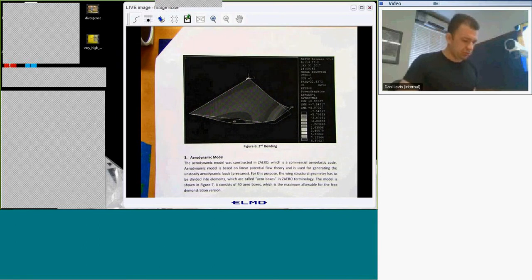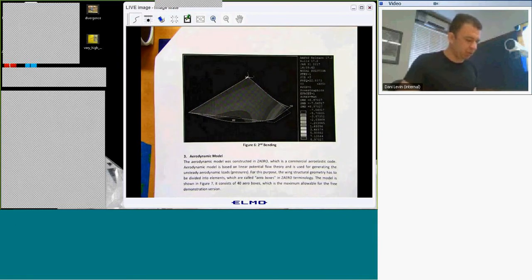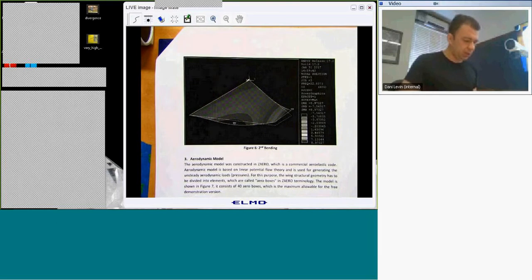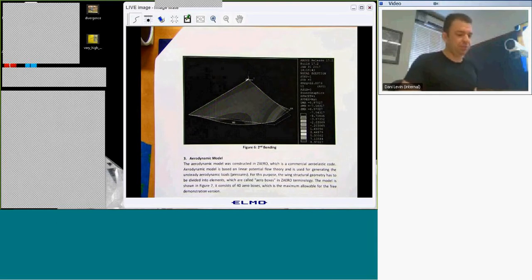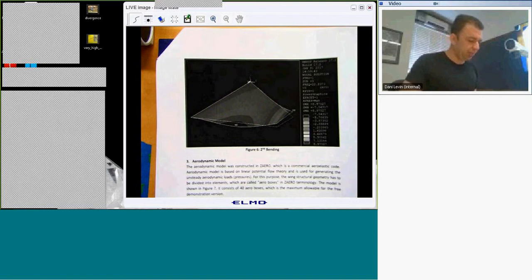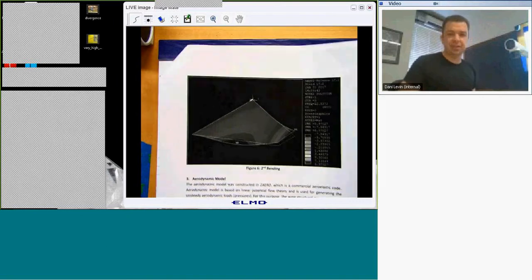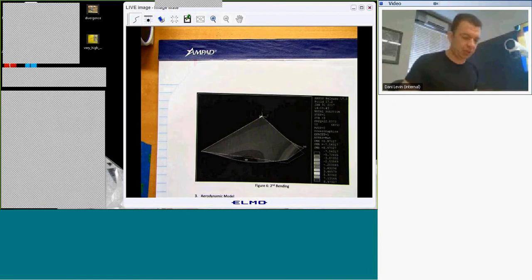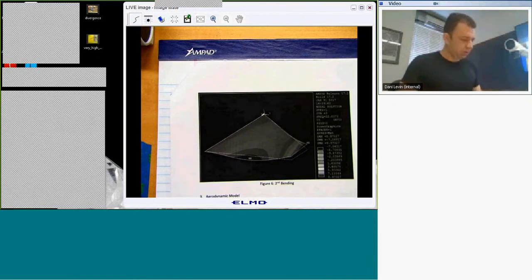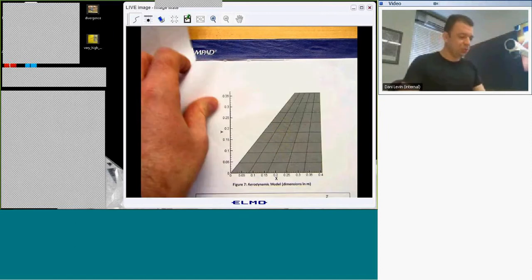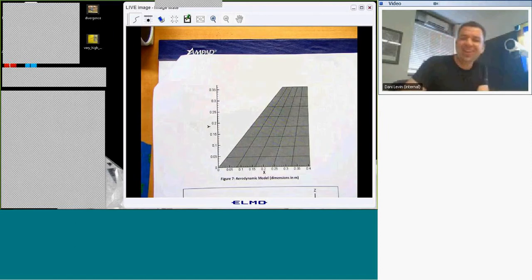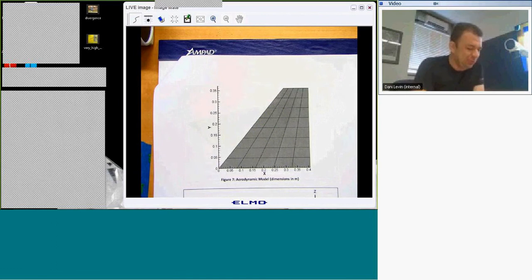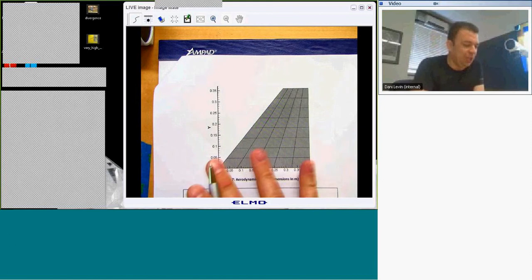Okay. So now we've established our structural model. The other part of aeroelastic analysis is the aerodynamic model. The aerodynamic model is the one that will generate the non-steady aerodynamic loads. Okay, so all that you need to do in commercial code is just say where your plate elements are.